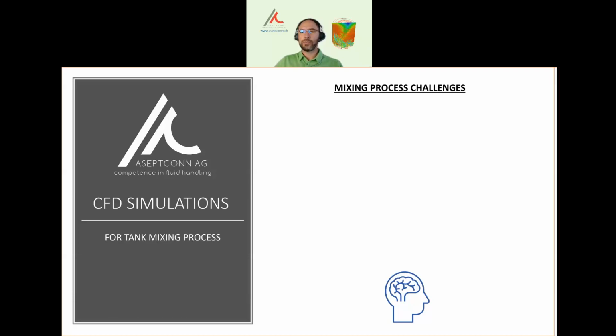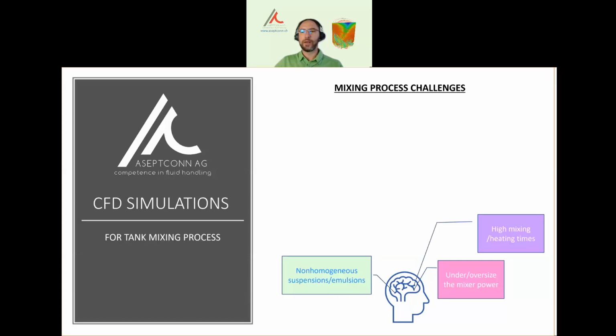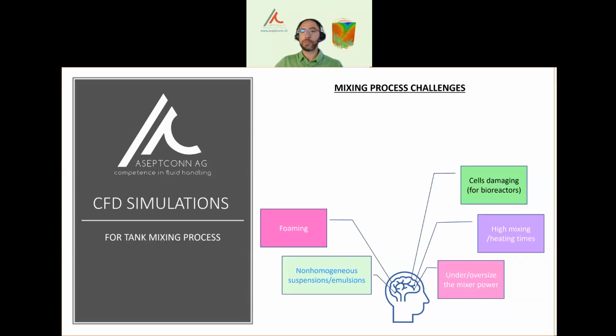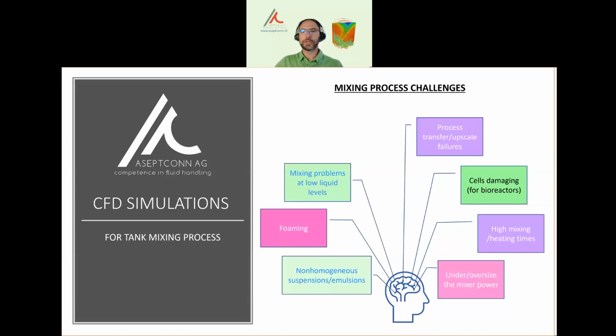I would like to give you some examples of issues: under and oversized mixer power, non-homogeneous suspensions and emulsions, high mixing and heating times, foaming, cell damaging, especially for bioreactors, mixing problems at low liquid levels, process transfer and upscale failures, overheating of sensitive and explosive products.